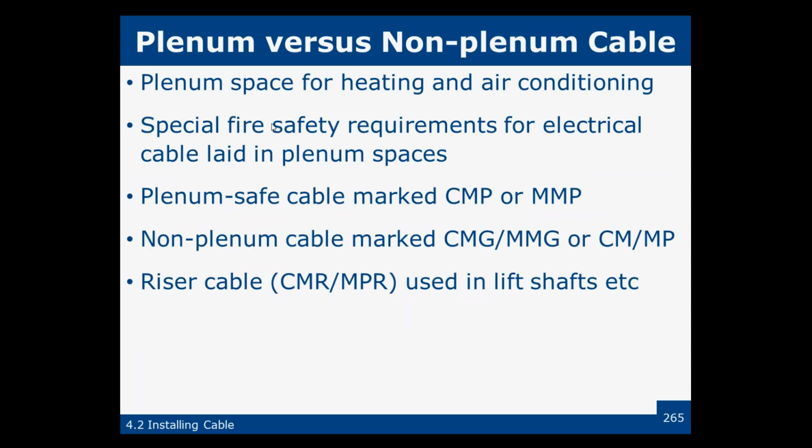And then we have plenum versus non-plenum cable, and we talked about that a little bit earlier. The plenum cable is designed to go into air spaces. The plenum is a space for heating and air conditioning, any place that we're going to have air movement.